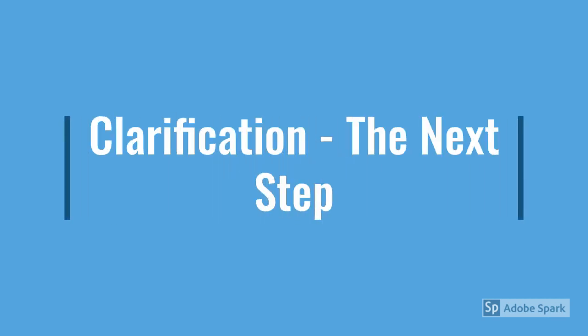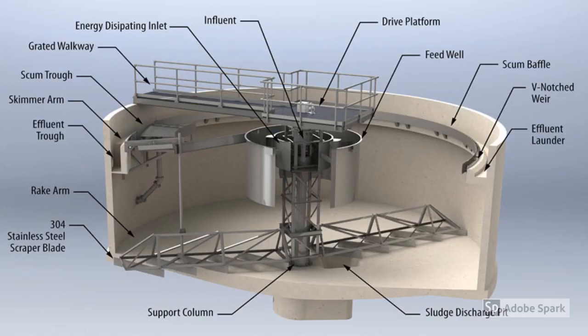The next step in the water treatment process is clarification. Water leaving the biological treatment is pumped into two clarifiers, each holding 2.6 megalitres. The clarifiers are of a conical construction, allowing sludge and other particles to settle down towards the bottom of the cone and be collected and returned to the effluent intake of the biological process via return activated sludge or RAS pump.